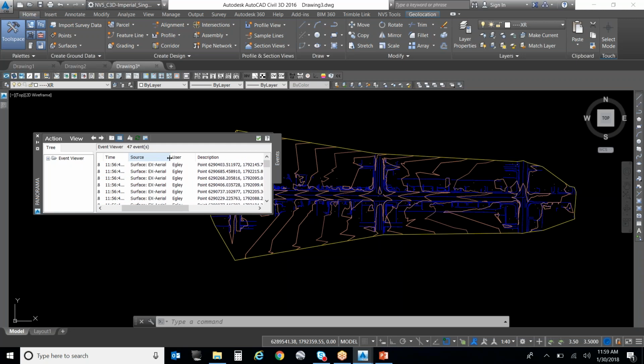Be very careful doing that because AutoCAD will remember that setting next time you go to insert a block. So just be aware of that. Sometimes it's better to just insert it and then select it and explode it, just so you're not changing that default value.